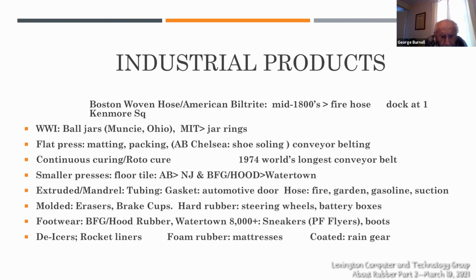So we have continuous curing, and the way they do that is they have two belts that are endless belts. And they go around a huge drum, pair of drums, if you will, at one end, and then the belt runs along a heater, which cures it, and then exits between the two belts.